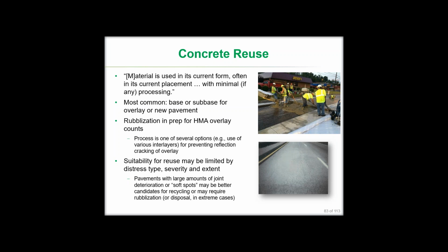And this is the most common application, using as a base or a sub-base for an overlay, often an asphalt overlay, or for a new pavement as we're seeing here, an unbonded concrete overlay, or in this case a bonded concrete overlay. I noted earlier that rubbleization in preparation for the placement of a hot mix asphalt overlay does count as still reusing the concrete in place, because the process of rubbleization is one of many options that are available for the prevention of reflection cracking. It's not inherently necessary for the use of that pavement. It's just a selected approach.